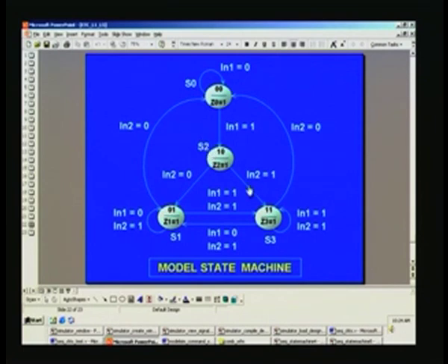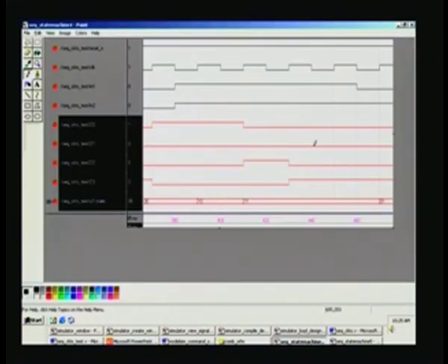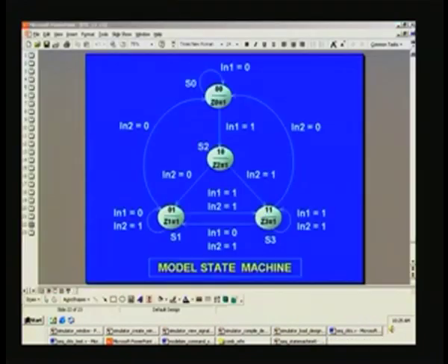So, we were in this, right. So, 0 1 would take you to S1 state. So, that is it. This one, the 0 1 here, right, and I hope you have kept track of all the LEDs for Z0 through Z3. In fact, I forgot to mention, but you can see one of them you can verify here. So, for 1 0 state, same thing you should get here, Z2 must go. So, 1 0 is 2, so Z2 must go high. So, this verifies at random, and finally we have one more waveform in the state machine.